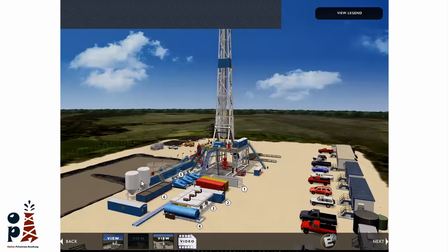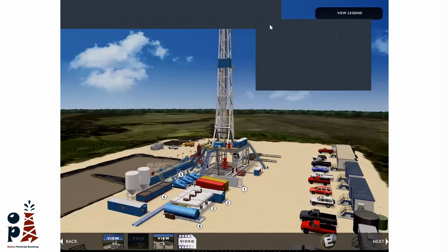So we have two ways to bring them: in big bags, every one is 1 metric ton, or for barite 1.5 metric ton. Or simply we can use this silo. We can bring the barite or bentonite on trucks and fill the silo, and we can use them easily instead of big bags. This is an alternative way, but as I told you, it is not common. You will not find it a lot when you go to the rigs, but some rigs use this bulk silo.